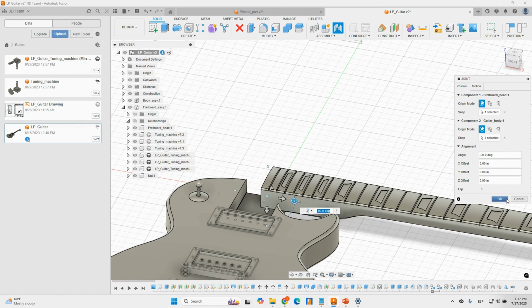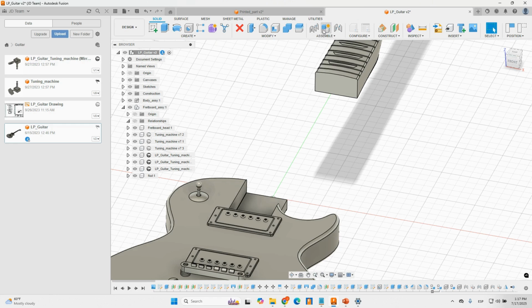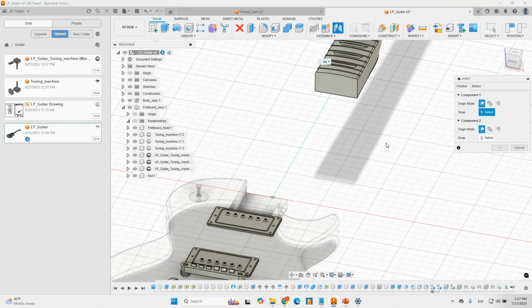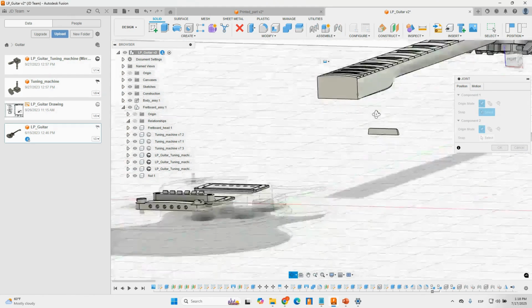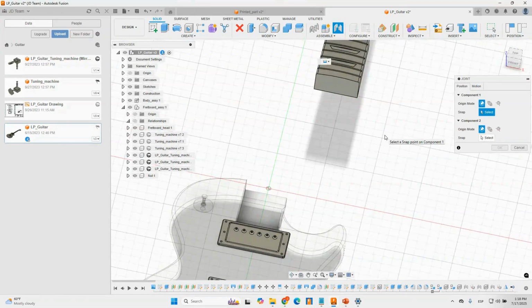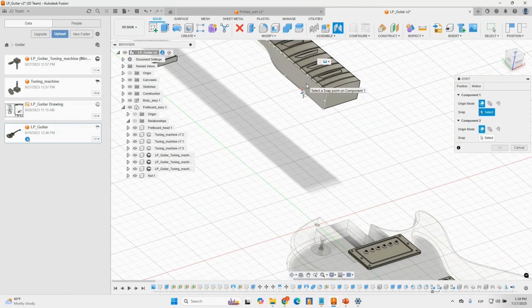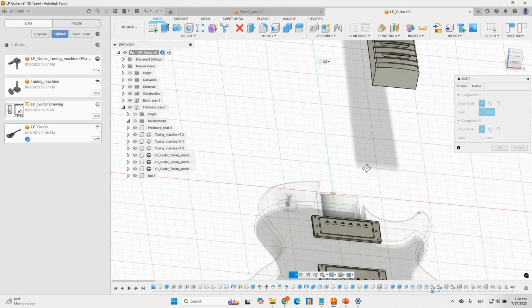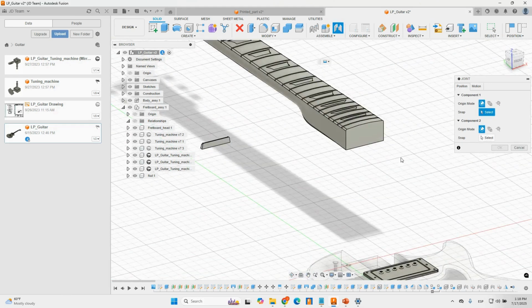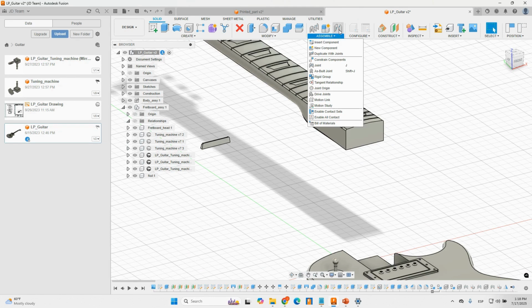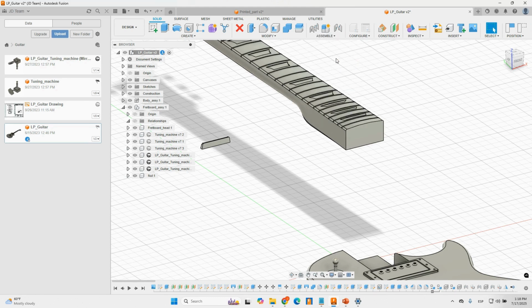But if you don't have a certain reference, like a physical reference to grab your origin point to, or if you want to specify another type of movement, maybe you're a constraint kind of guy, right? That is probably you want to reference a face, okay, to match another face, right? And Fusion only let you create this type of joints before, right? So with this latest release, you don't need to only use joints. Now you can constrain components, okay?